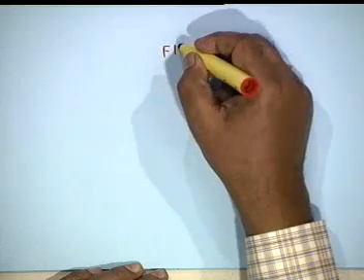Okay, this leads us now to the question. We have tackled IIR filters, and since lattice is so much a favored structure, what about FIR? Can we realize an FIR filter also by a lattice structure? Now, it is a historical fact that FIR lattices were not synthesized ab initio, they were synthesized by analysis, and we shall follow the same procedure. Do you understand the methodology?